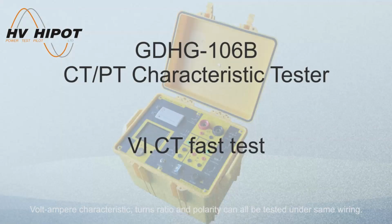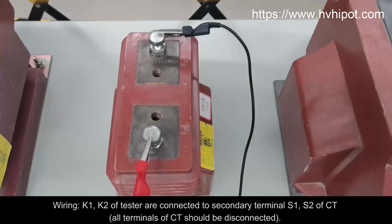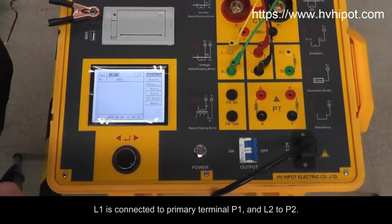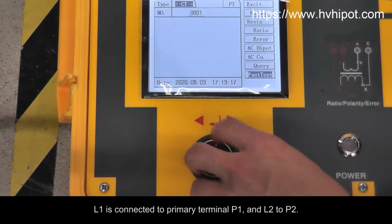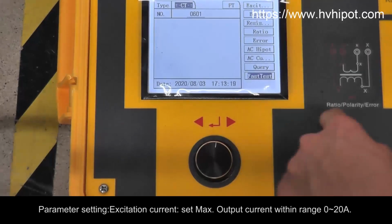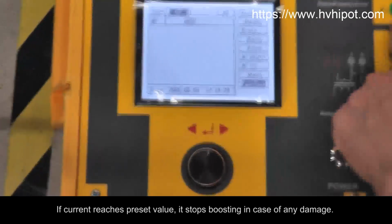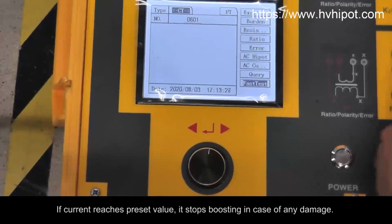Volt-ampere characteristic, turns ratio and polarity can all be tested under same wiring. Wiring: K1, K2 of tester are connected to secondary terminal S1, S2 of CT. L1 is connected to primary terminal P1, and L2 to P2. Excitation current, set max. output current within range 0 to 20 A. If current reaches preset value, it stops boosting in case of any damage.